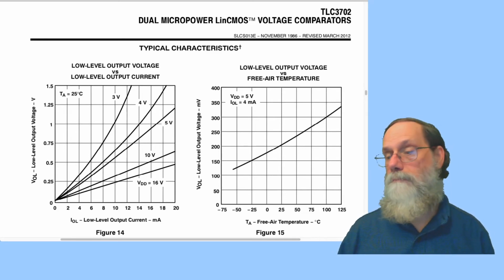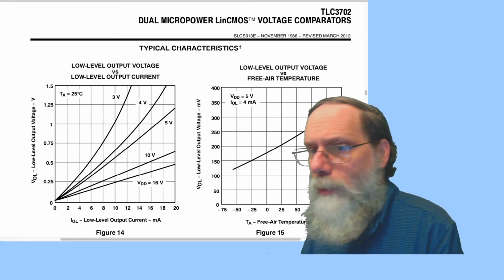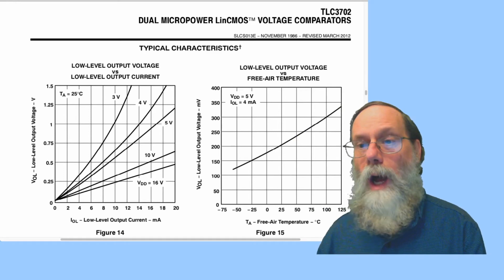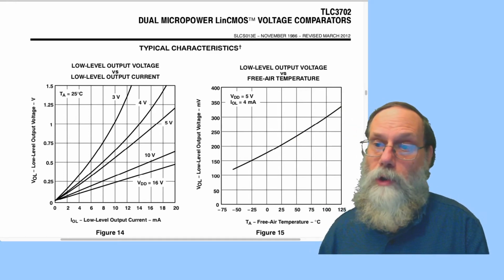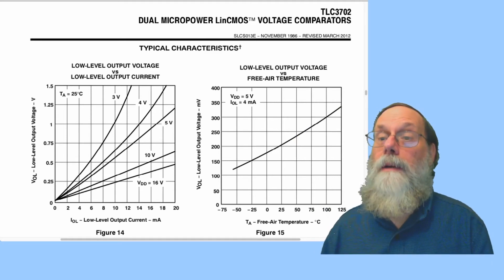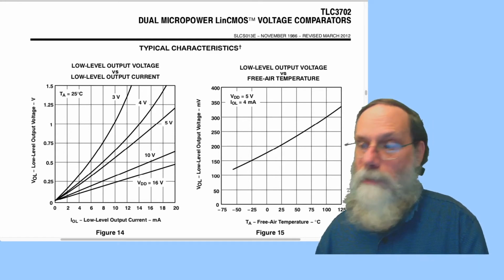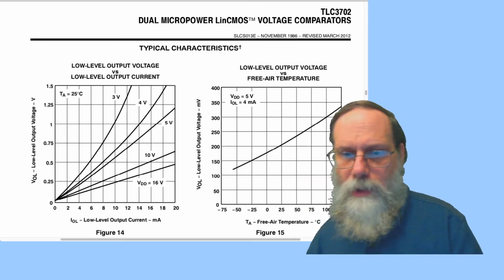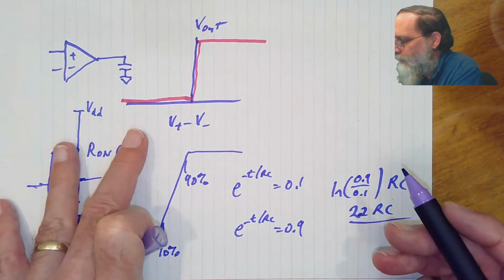All right, what else could we do? We could measure it. How would we measure the on resistance of those? Well, we just look at the current and the voltage. So we need to do something that will change how much current it takes and measure the corresponding voltage. Let's switch back here to paper and take a look at what we do.